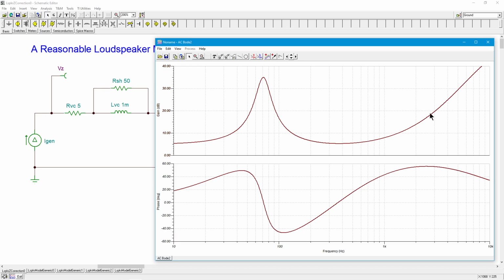And then this rise over here is again due to the inductance, right, the XL of the voice coil. So what I would like to do ultimately is turn this thing into a nice flat straight line at 8 ohms or some other value, but a nice flat value. And the same thing with the phase shift. Notice the phase shift over here is swinging about plus and minus 50 degrees. It'd be nice if I could get it to hover closer to 0 degrees.